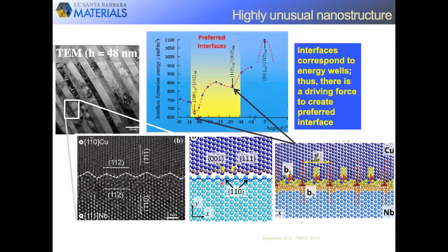So what we find is that the sawtooth morphology here can be expected due to the natural topology of these planes that are being joined. These materials, just a raw cut of these crystallographic planes, are atomically jagged periodically. But when you join them and create the interface, you do create a network of what we call misfit dislocations, that help glue them together without free surface.